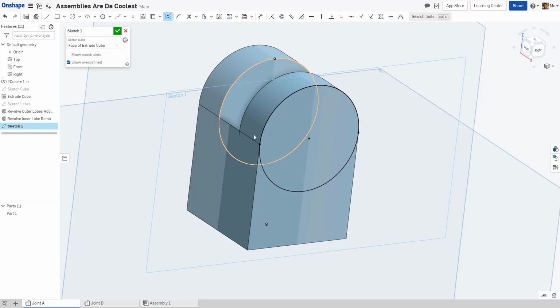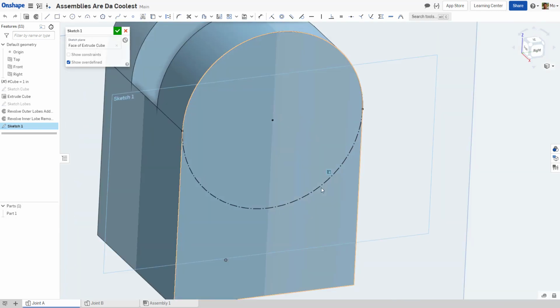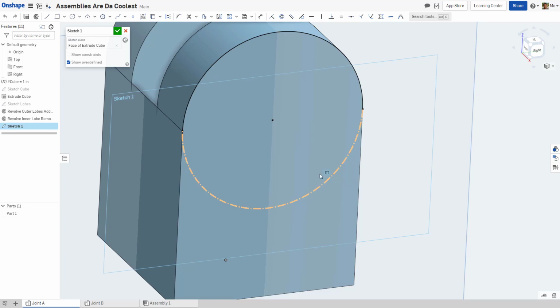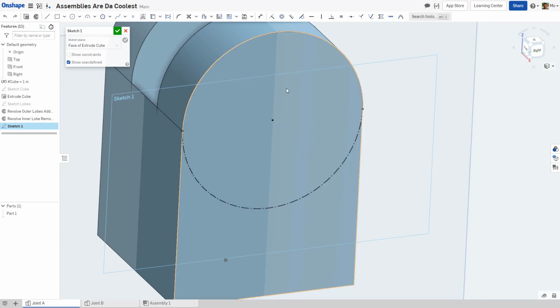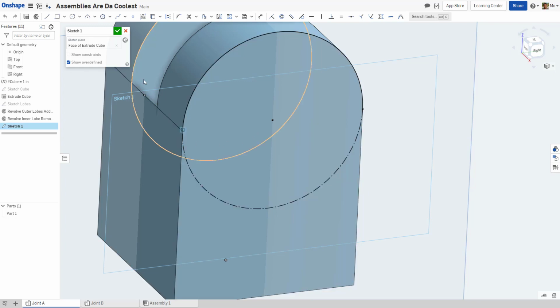Construction lines allow you to create geometry as a reference, rather than something that will physically be effective in an extrusion or a three-dimensional tool. When I click on this bottom line and choose Construction, you'll notice that the line turns into a dotted line. This line now only exists as a reference, rather than something that we can do something with. This tends to help declutter our workspace and prevent us from having to select multiple faces when using the Extrude tool. However, right now, we're not going to use the Extrude tool. I want to add one more feature, a point, at the center of this circle.